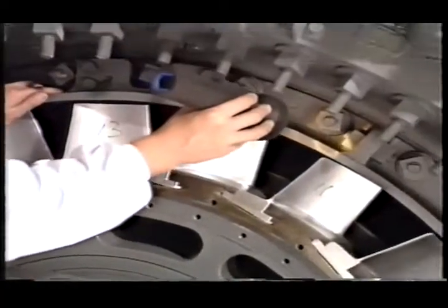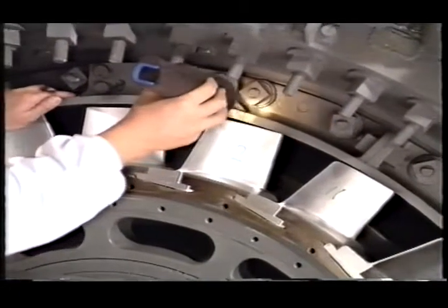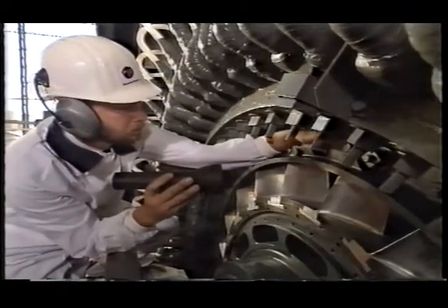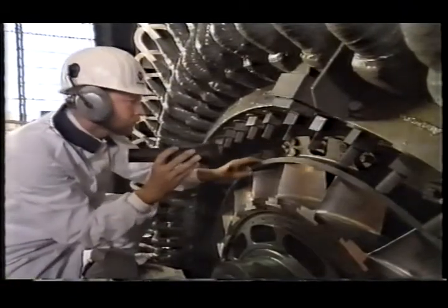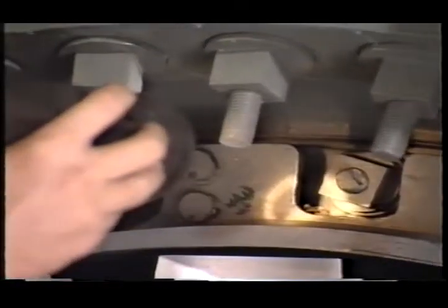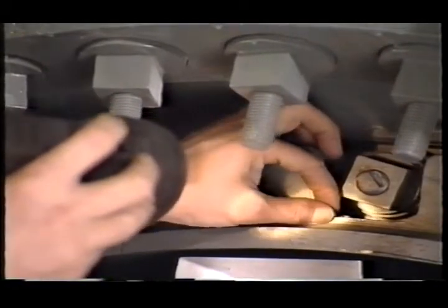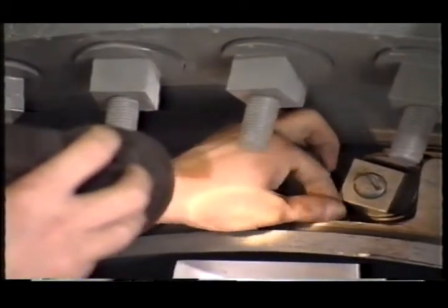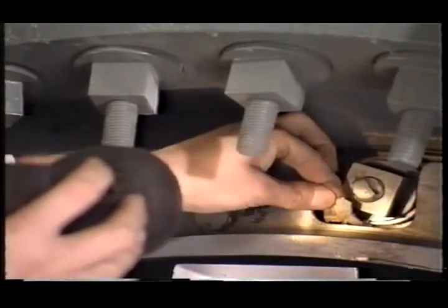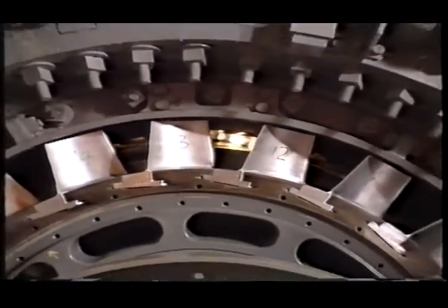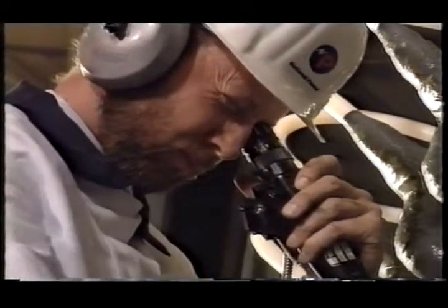When the work is completed, a detailed inspection of all areas of the machine must be carried out. This is usually the joint responsibility of the station engineer and the contractor's supervisor. Those areas which are inaccessible, including pipework, should be inspected with an intrascope.